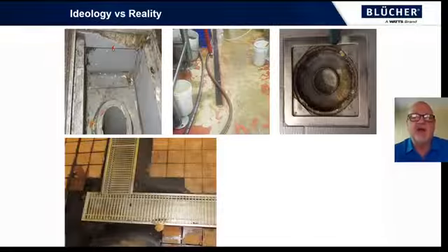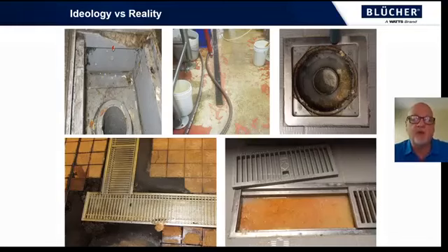Drains like this are common in a food facility, and they represent elevated and unnecessary ongoing operational costs due to the added cleaning and maintenance needs that they have. Additionally, they all represent a potential source of contamination. They all represent risk. I'm sure it's not going to surprise anyone to hear that the most common source of positive screenings in a food and beverage plant is the floor, and more specifically the drain. So looking at the sanitation of your process environment, you're going to be as strong as your weakest link. If that's the drain, let's see how we can make them better.